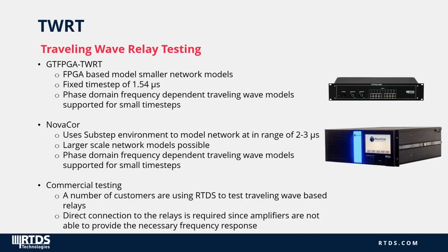Both of these approaches use phase domain frequency-dependent traveling wave-based models. A number of RTDS customers are using the simulator to perform TWRT testing. A direct connection between the simulator and the relay is required since amplifiers do not provide the necessary frequency response to test these high-speed relays.